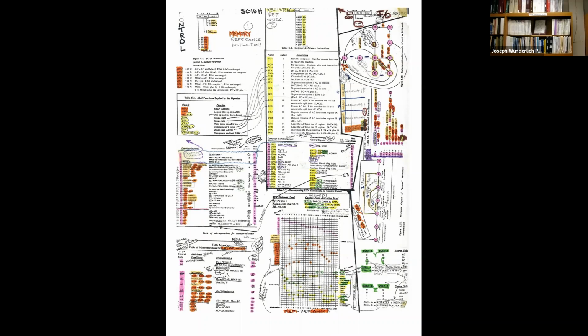And then when you look on the right here, sideways, those are the finite state machines that we learn how to design when we do sequential circuit design. We do digital and sequential circuits. Sequential circuits yield finite state machines, or are implemented with finite state machines. And that's how you actually execute the instructions. That's what sets up the machine instruction cycle and the stages of the pipeline.